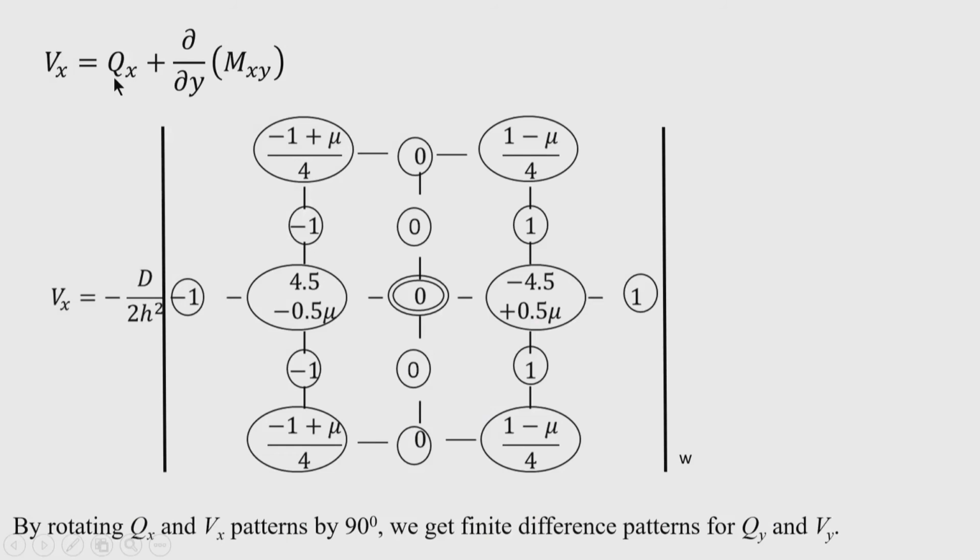So, 3 conditions are necessary, and these 3 conditions of free edges are given by Poisson, that I told in my earlier lectures. Now, the 3 conditions are combined by Kirchhoff mathematically to give 2 conditions. So, one condition is bending moment and another condition is effective shear. In the effective shear expression you will find that 2 quantities are involved, that is Qx and Mxy. So, twisting moment and shearing forces are combined to form the effective shear force expression.